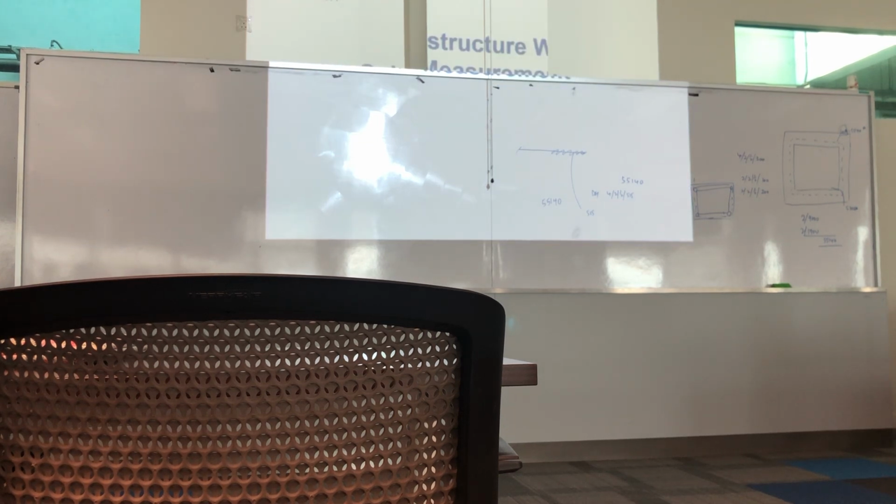Substructure works measurement, right? So what do you do? This is a few of the things that you will do first when you come to a site, right? Before you even talk about floor finishes, before you even talk about erecting the walls and whatnot, right? So the first thing that we do is to do site clearance, right? Like what I said, you observe the site across the road.